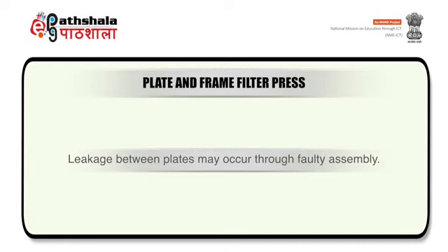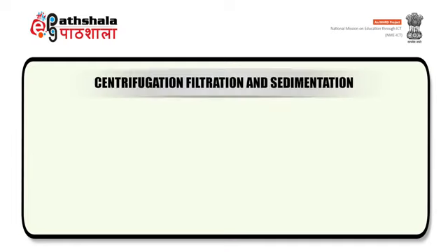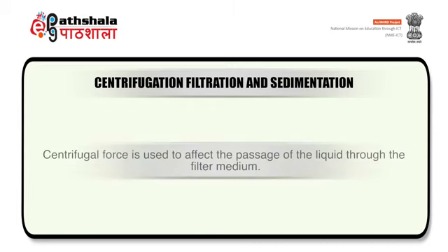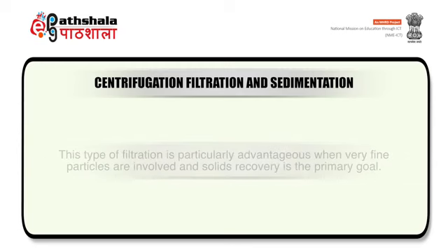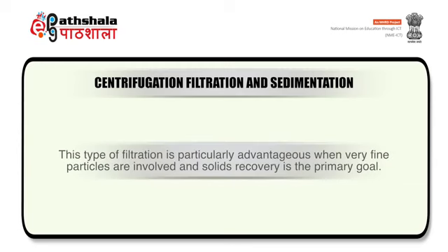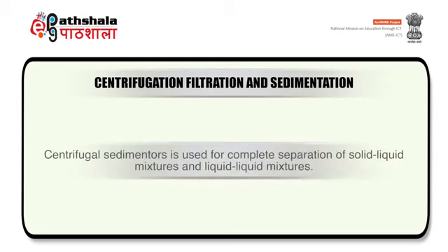Secondly, leakage between plates may occur through faulty assembly. Now come to the topic centrifugation, filtration and sedimentation. Centrifugal force affects the passage of liquid through the filter medium. Filtering centrifuges are used for filtration of very fine particles and where solid recovery is the prime goal, whereas centrifugal sedimenters are used for complete separation of solid-liquid mixture and liquid-liquid mixture.